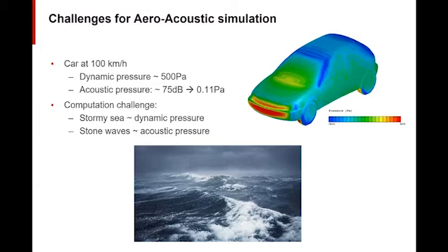And that's a challenge in aeroacoustic simulation. Now I'm going to talk about the different approaches to solve aeroacoustic problems. SC Tetra, a CFD software, can be used to predict the flow-induced noise using the following methods. We have two methods called the sound source detection method and the acoustic analogy method to predict the acoustic performance. And hybrid methods, by coupling SC Tetra with Actran, can also be used to simulate this problem.